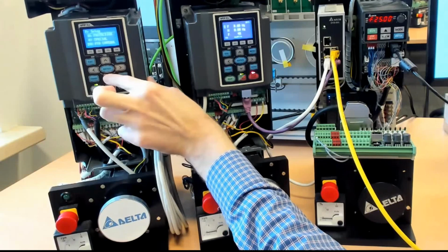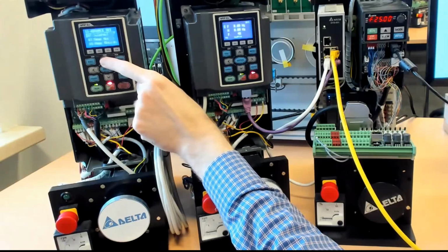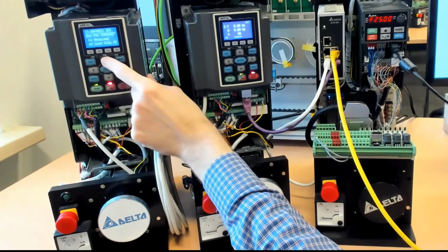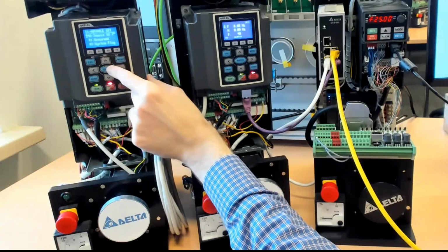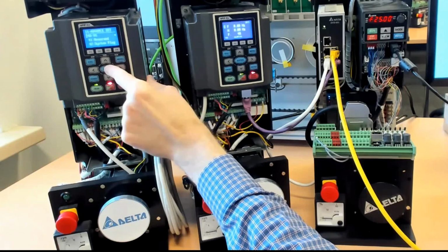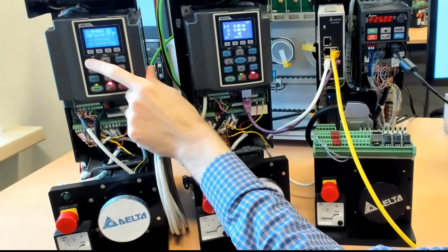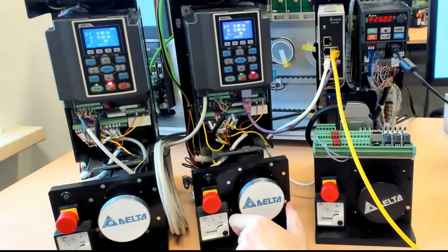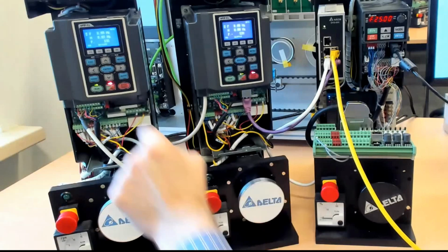And finally, since we're running the follower drive in positioning mode, you also need to tell it what is the source of positioning. Then you have 11-40, I think, source of positioning, and you need to tell the drive that it's coming from an external pulse. And this is basically it. After you configure the drive in field-oriented control mode, you just need to set these 4 parameters, and you're ready to start.